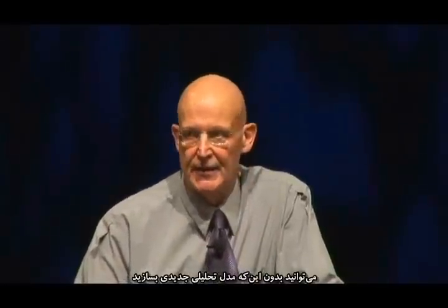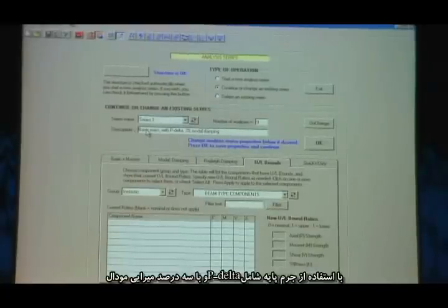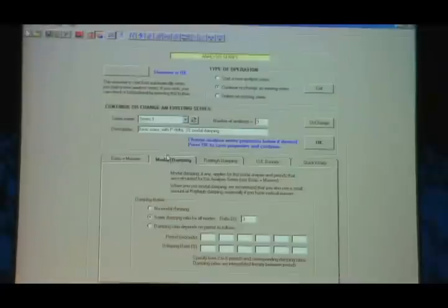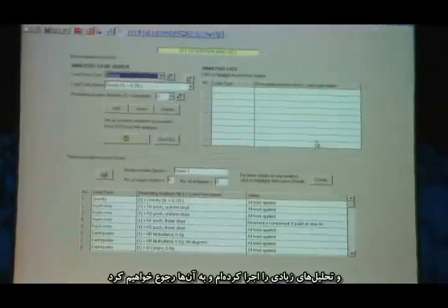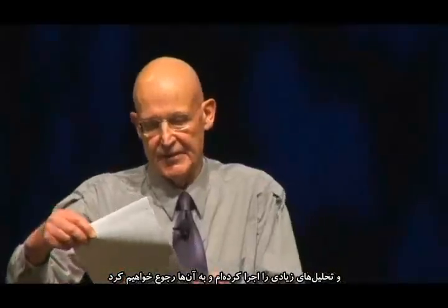So you could analyze one structure which is rather weaker and another structure which is rather stronger without creating a completely new analysis model. I've done just one analysis series here. It uses some basic mass, it includes p-delta, and it's got 3% modal damping. And I've already run a number of analyses.